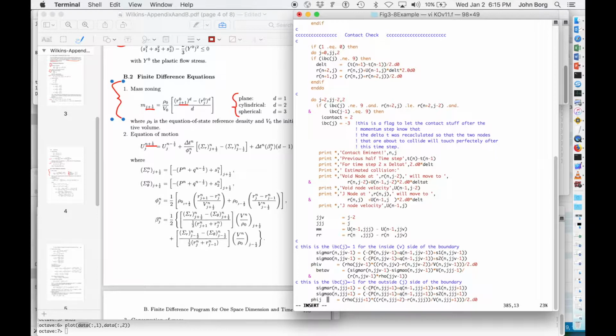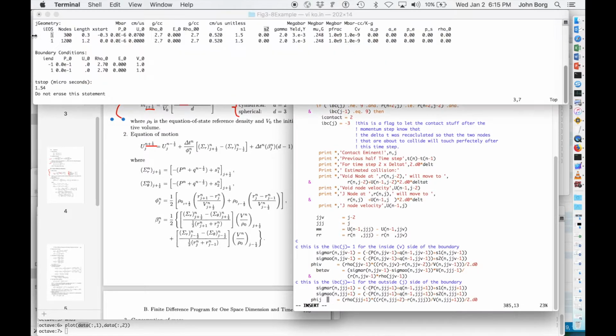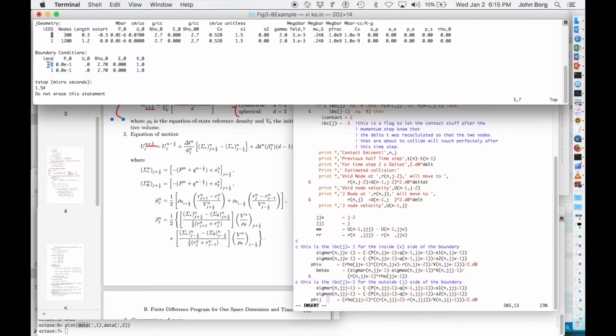So when nodes are initially discretized, they are assigned a value. Every node is assigned a value, whether it's essentially a boundary condition, and it lets the code know what stencil to use. If it's assigned a value of 0, that means it's a central difference node. Back when we were looking at the input file, the left node and the right node in the boundary condition file are assigned IBCs of either -1 or 1. This means use a second order left stencil or a second order right stencil, respectively, for those nodes.